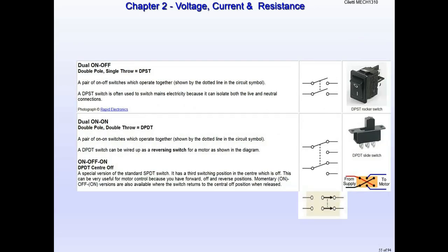This is a double pole, double throw. All right, so on this one, there's two circuits being closed at the same time. And two actual latches closing at the same time too. All right, so this is a double pole, single throw. Those two latches are connected at once though, so don't get super confused here. Look at the second one. There's a double pole, double throw. Now there's two latches, and it can control two circuits. Where on the first one, there's two latches that control one circuit.